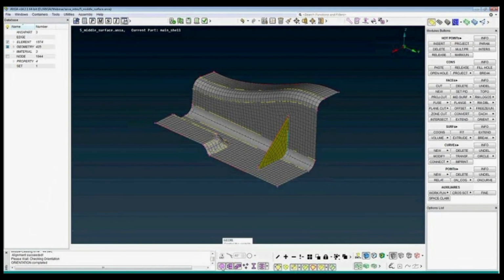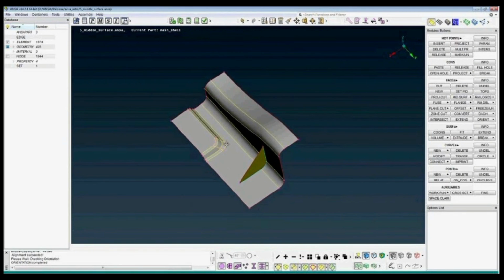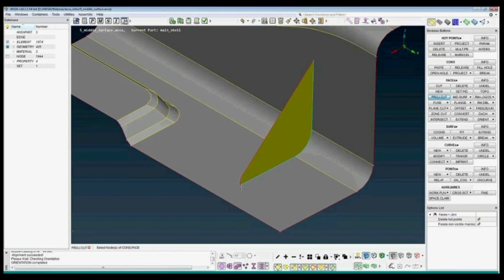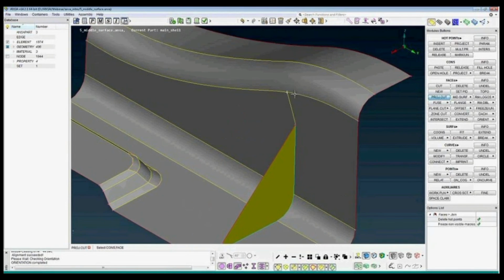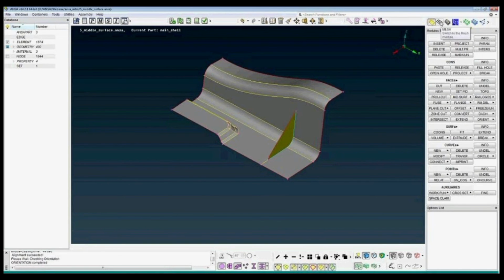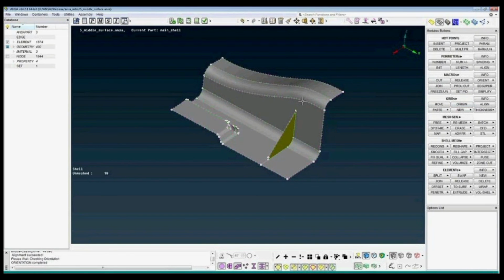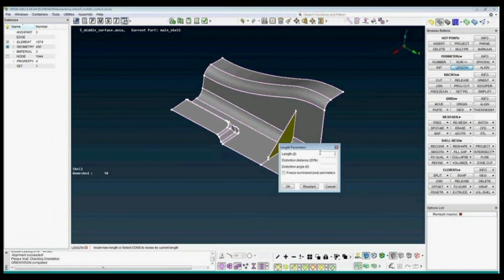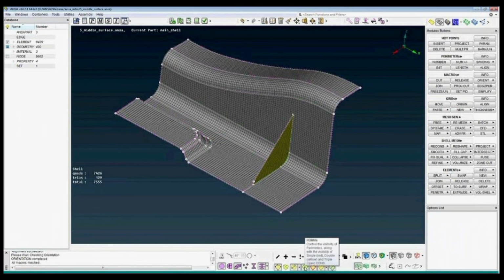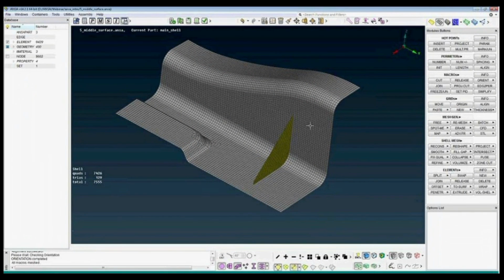You can switch to the top menu. We have the FE model. From the FE model I created the geometry. This geometry can be worked with as normal geometry. We can make projections and cuts. And then mesh it. Change the element length. So it was a short example of middle surface.